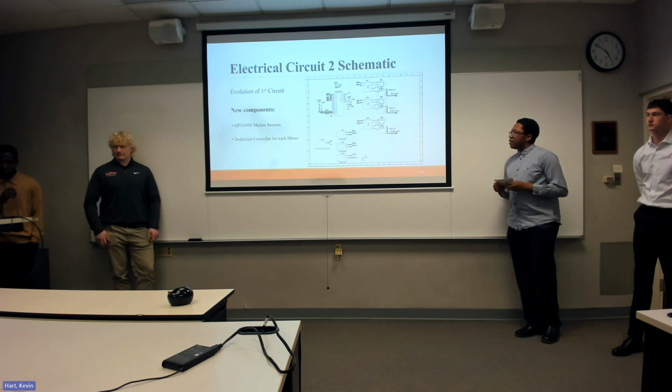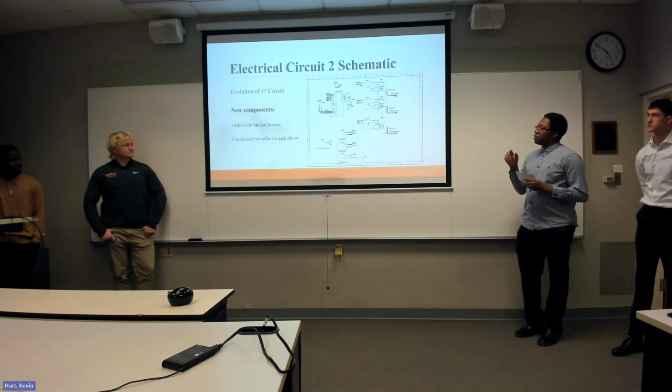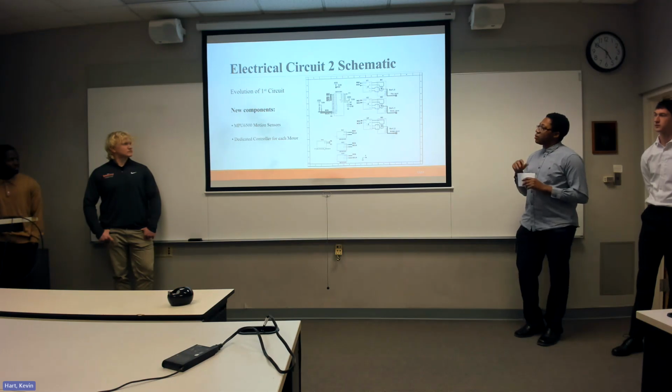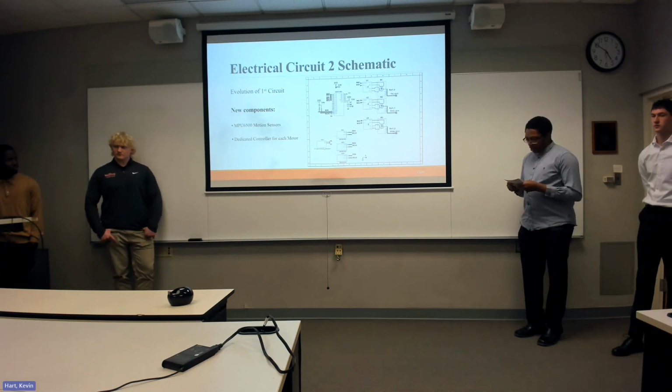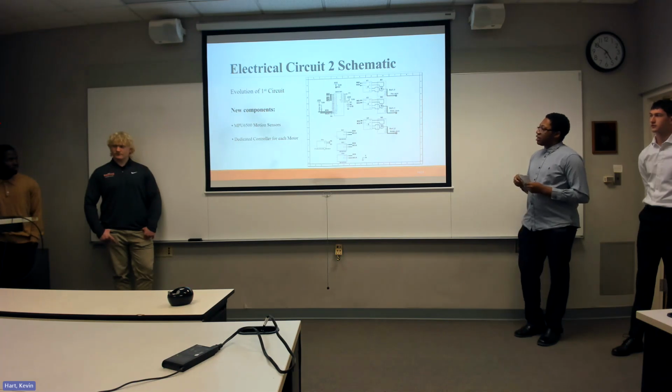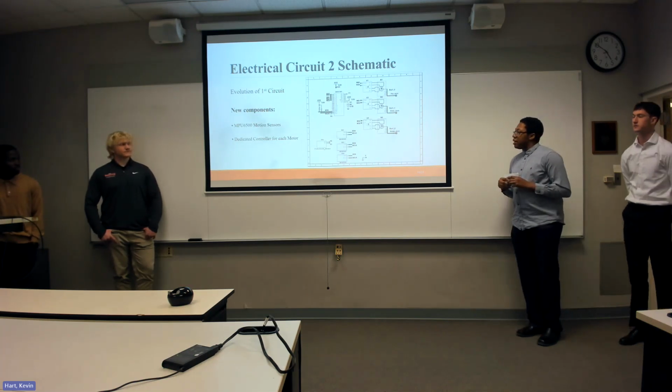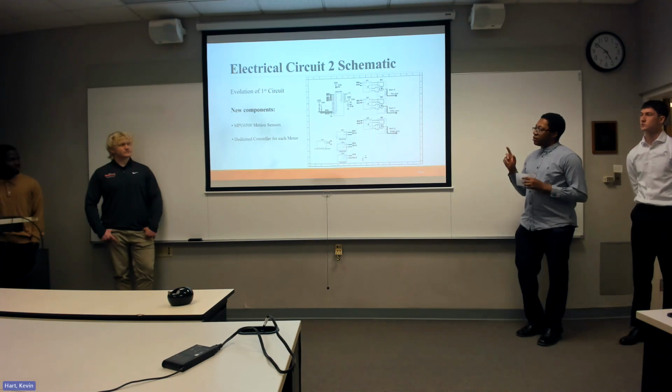This requires pull-up resistors, usually around 4.7 kilo ohms, that are connected to the operating voltage, which would come from our microcontroller. And then these must be connected in parallel, which means on the software side, we need to use addressing. A multiplexer may need to be used to add further addresses.